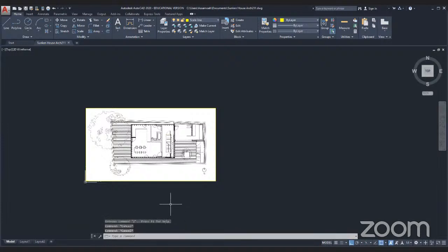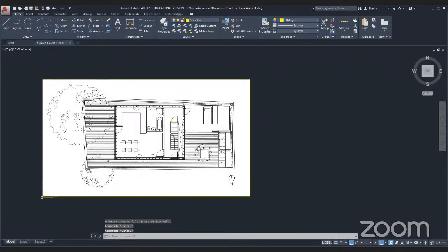Either way, once you save your document for the first time, it should activate the autosave feature. Otherwise, we have to go into our settings to make sure it does that. But either way, this plan is now saved to a particular scale, and we can go about tracing it to get a hardline AutoCAD generated drawing.